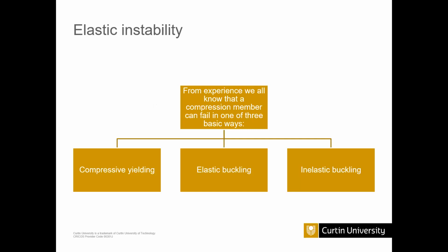Basically in buckling, you should know what failure mechanisms are available. In elastic instability, we know that buckling normally happens with compression. It cannot happen with an axial tensile load. With bending it can, but basically with axial load. With torsion it will not buckle. Are you agree with me? With a compressive axial load, only then can it be buckled.